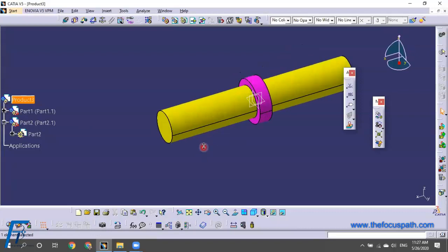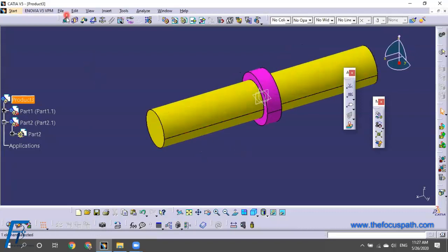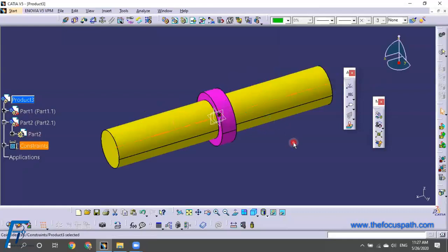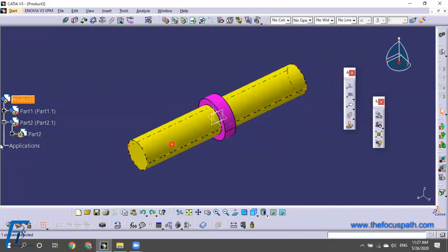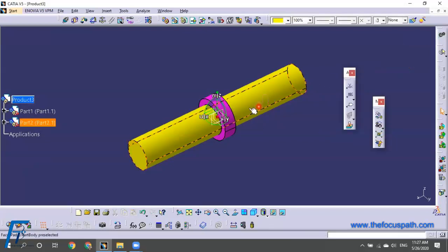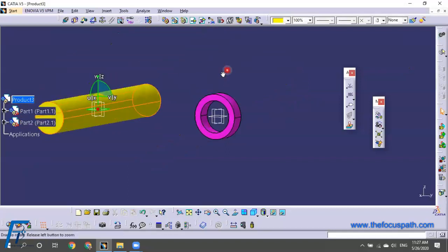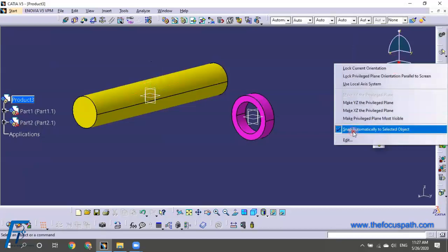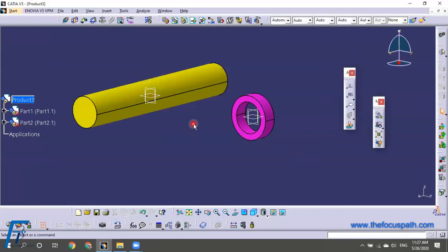Okay. So in this case, once again, you give an assembly constraint. There is no meaning of giving an assembly constraint. See here it takes. Very important. Understood? Here it takes. Why? Sketch and sketch is only connected. There is no other dimension. So what I can do, I can use snap, move this component anywhere. That means the sketch and sketch only is constrained, but not the assembly constraints. You need to be very careful on that, right?